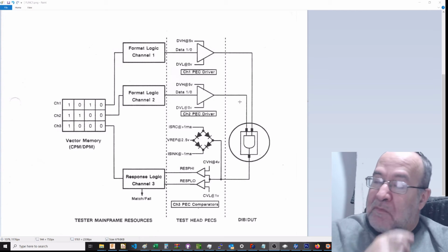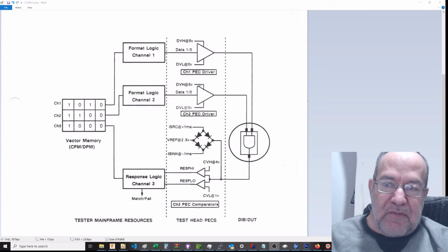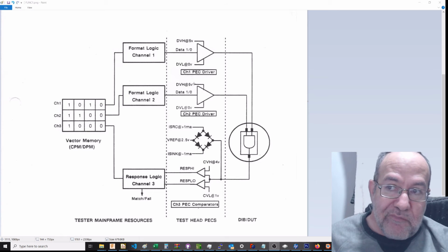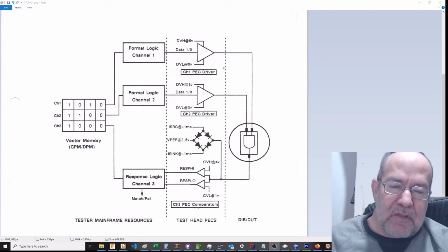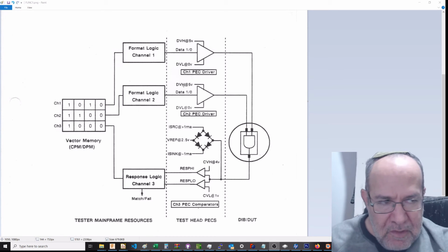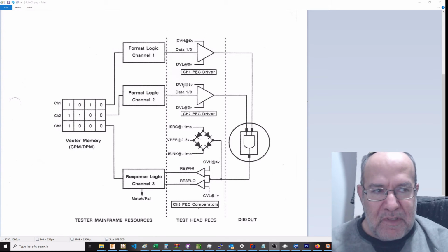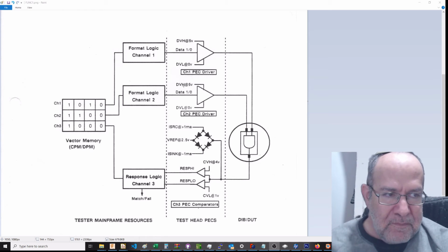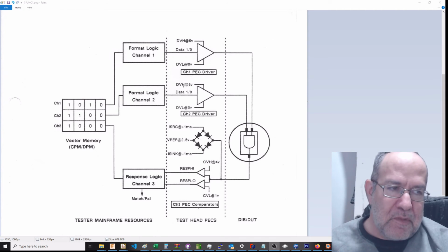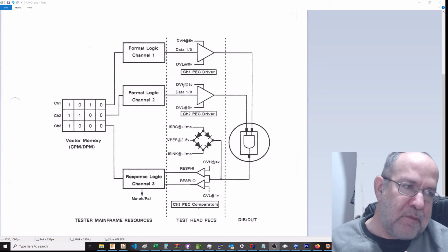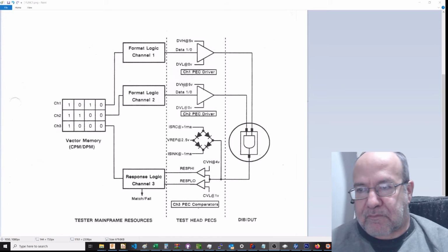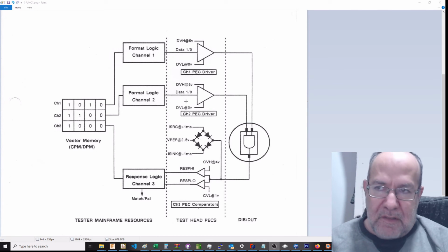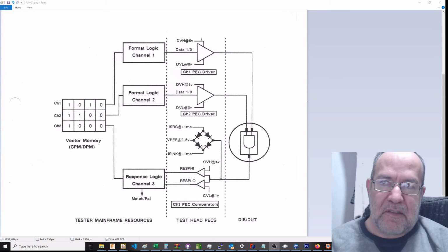Okay. DVL. Okay. That determines your voltage. Now, if one goes through a data sheet, one will see what is the minimum that you can have which is considered high, what's the highest value which is considered low. Okay, these are these parameters here, DVL, DVH.